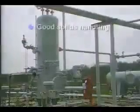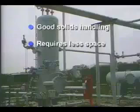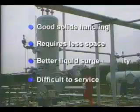A vertical separator, on the other hand, has good solids handling capability, requires far less space than a horizontal separator, and has much better liquid surge capacity, but it is more difficult to service.